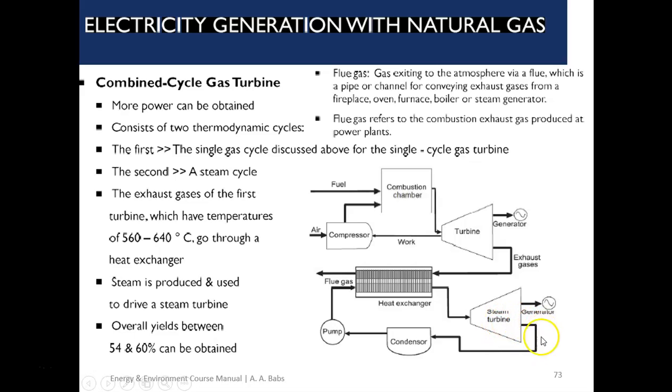The steam generated can be collected by the condenser. It is condensed into water. It is then again pumped back into this heat exchanger. When this heat from exhaust gases is collected, the heat boils water that is also pumped into this heat exchanger. It is that water that then turns to a high pressure hot steam that then turns this turbine. And then the steam that is collected after the turbine has turned the generator is then collected and pumped back into the heat exchanger. So the steam cycle continues here, and then we have the gas cycle here.